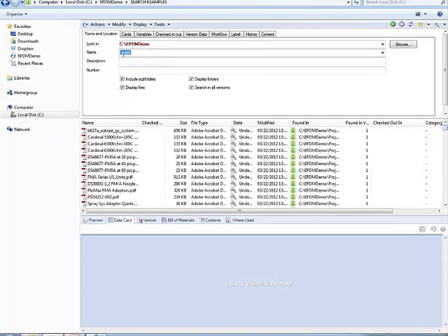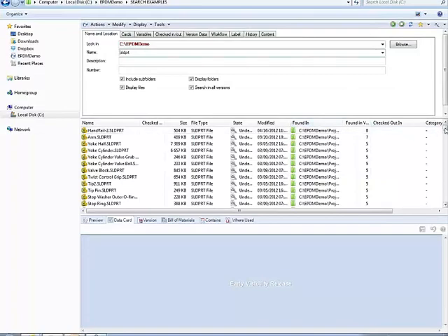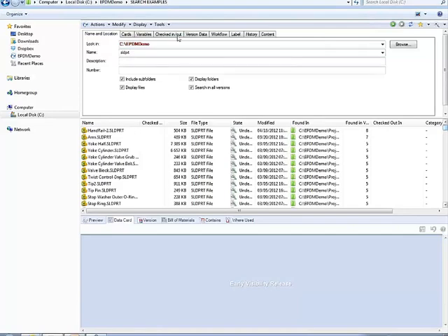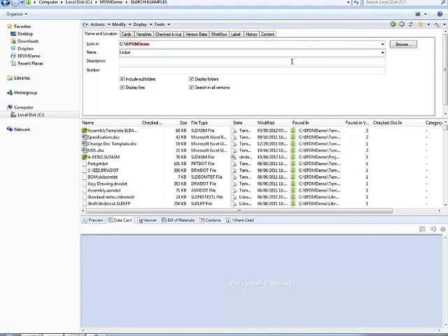Just so that you know I'm not pulling the wool over your eyes, I'll search for SOLIDWORKS part files, and you'll see that I have several of them in my vault here. So we can use the exclamation point to exclude as an exclusive syntax in our search results.